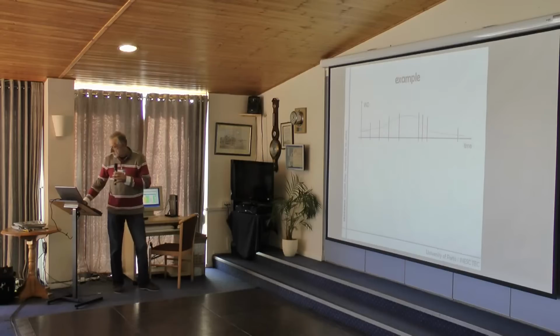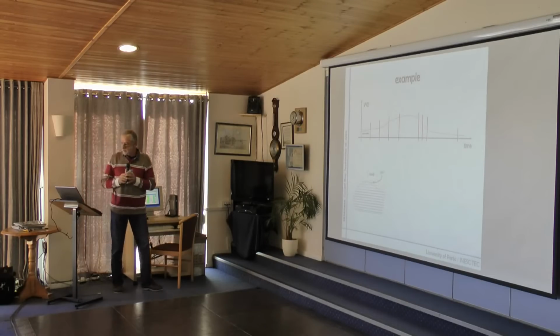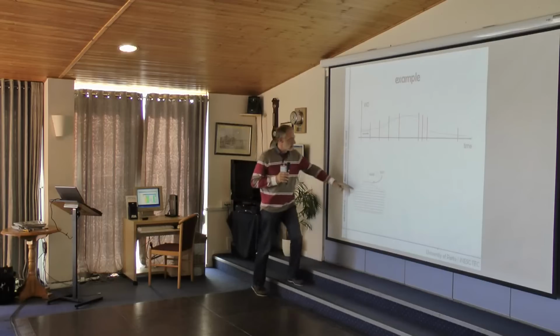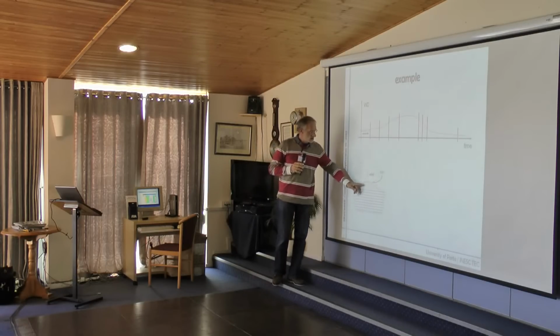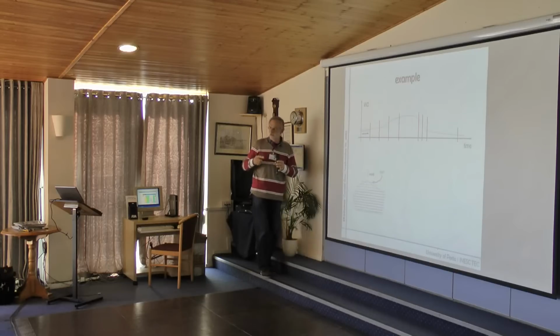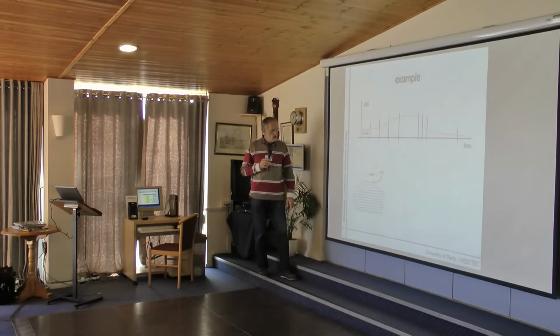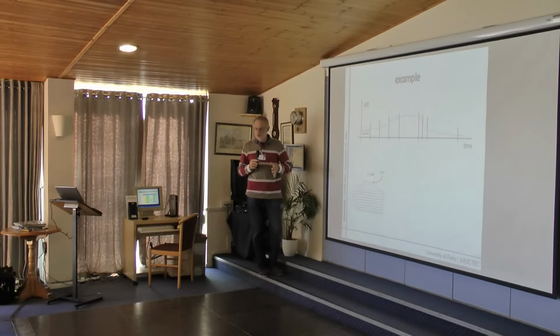And then, for the first time interval, we set up a scanline navigation pattern like this. Okay, we start in the upwind point. We can either start on the right or on the left, and this will affect the transition for the next area scan. Start scanning this area with a navigation more or less perpendicular to the wind direction, okay?